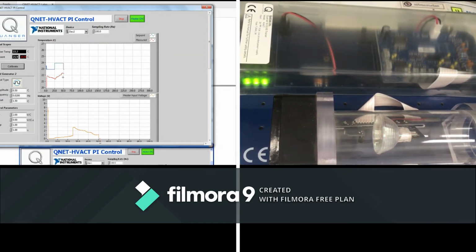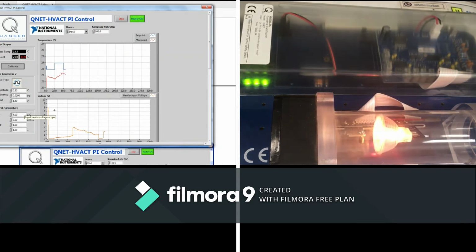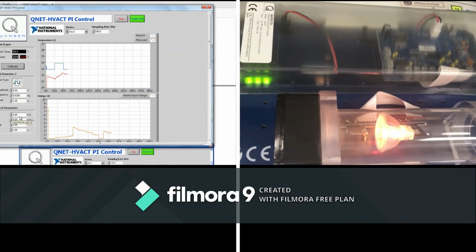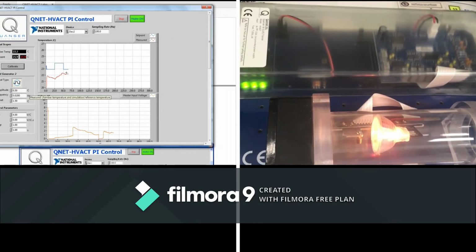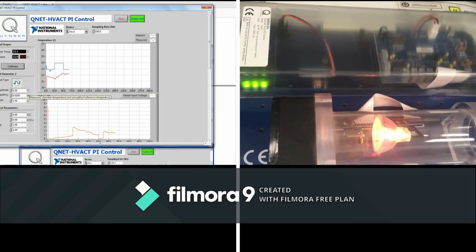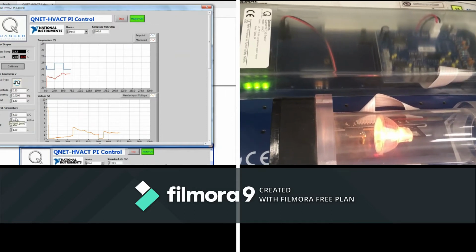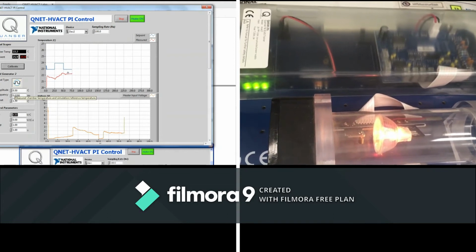This is 50. Now we can go and see 4, for example. So starting from 50 to 100, the value of KB will be 4. And you see that we can see the difference. The gap between the set point and the actual value is high, and now with KB of 4, the gap is reduced.